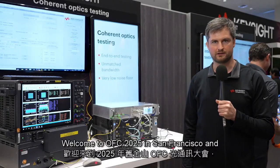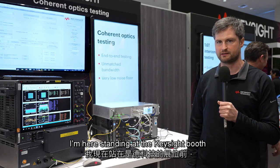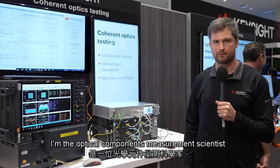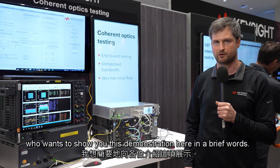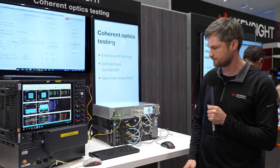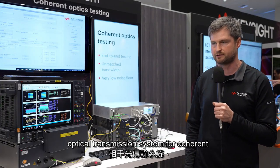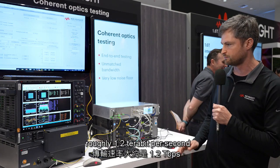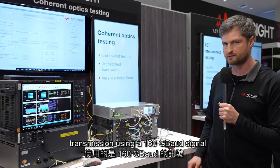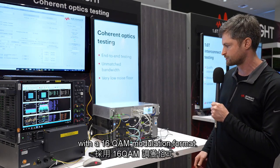Welcome to OFC 2025 in San Francisco, and I'm here standing at the Keysight booth on coherent optics testing. My name is Jörg Pfeifel, and I'm the optical components measurement scientist who wants to show you this demonstration. In brief words, we're mimicking here a complete optical transmission system for coherent, roughly 1.2 terabit per second transmission using a 160 gigabaud signal with a 16 QAM modulation format.